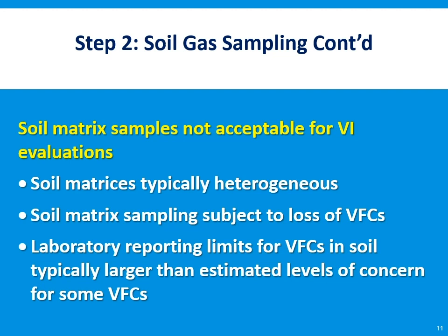Again, soil samples or soil matrix samples should not be used for vapor intrusion evaluations. Soil tends to be heterogeneous, and soil gas samples are typically representative of a larger subsurface area than a soil sample. Furthermore, soil samples are subject to vapor loss even when using strict Method 5035 sampling procedures. Also, laboratory reporting limits for soil samples are typically higher than vapor intrusion screening levels. Hence, soil samples should not be used for vapor intrusion.